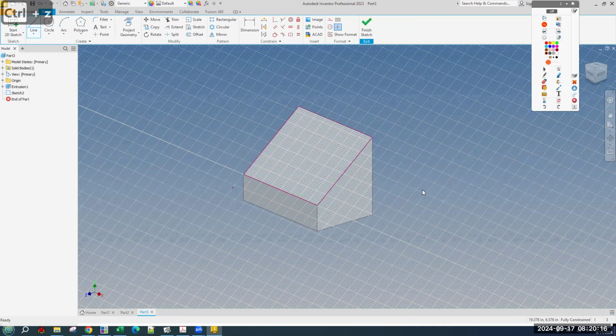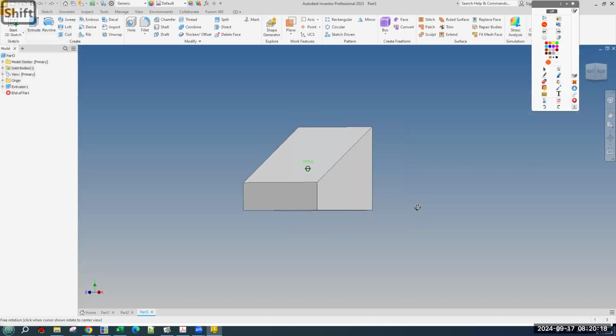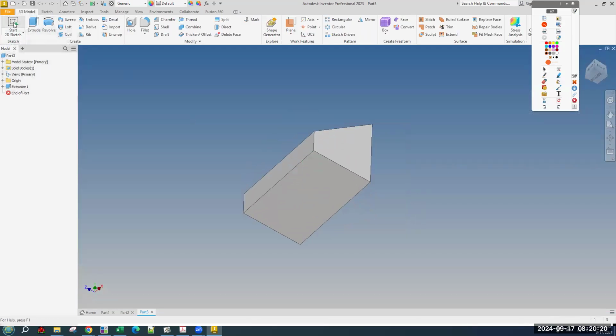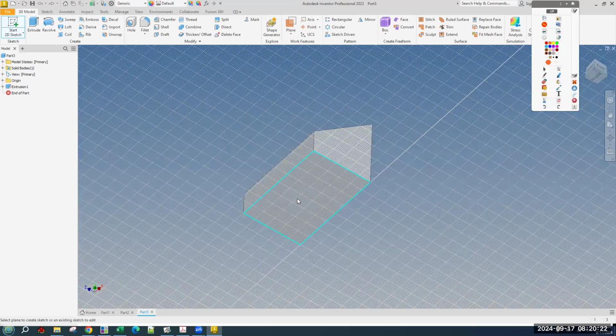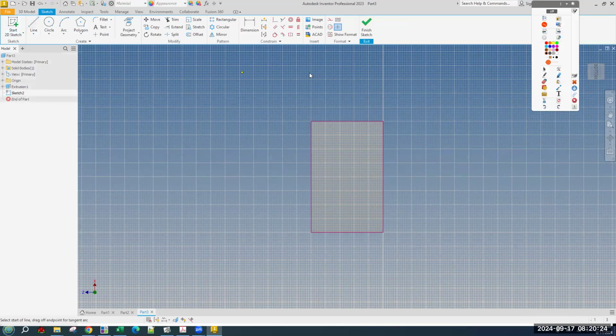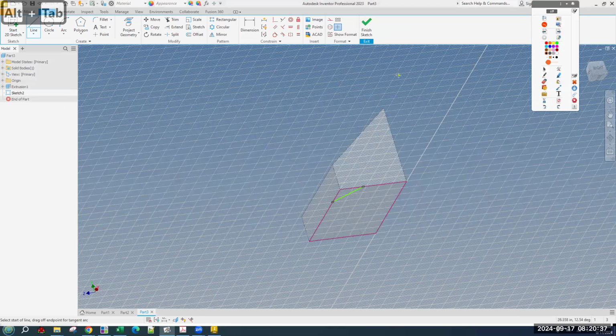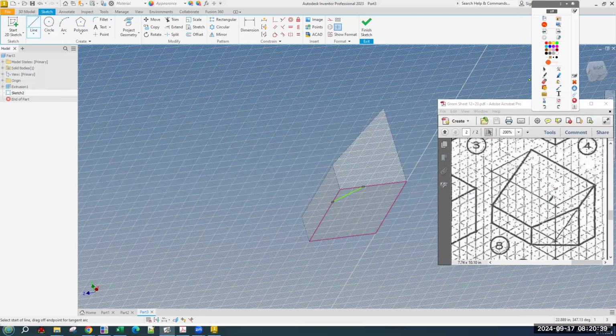Because extrusions go perpendicular to whatever plane they're on, it's going to cut in that way. So the 2 ways are, one is putting a sketch on the bottom, like here, in which case the distance here is 3 back in either direction.